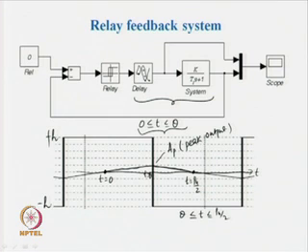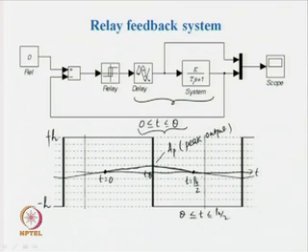So, it is evident that we have to consider two different piecewise constant inputs to the system during the positive half output of the system. The output is a sustained oscillatory output. Therefore, we need not consider the whole period of the output signal; rather, concentration will be on one positive half period of the output signal, which carries enough information as far as the dynamics of the system under relay test is concerned.